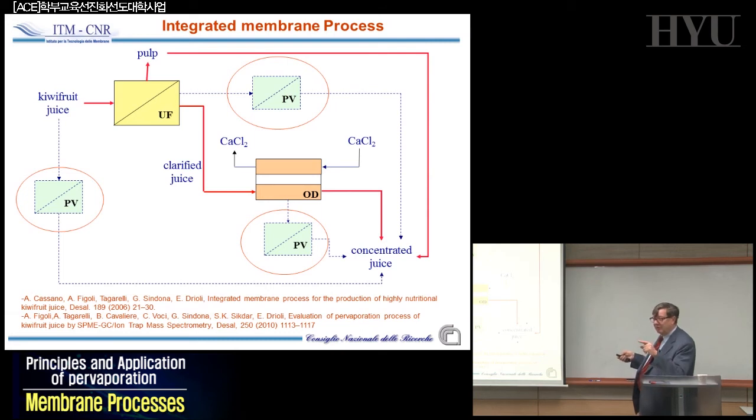But you know that in membrane distillation, part of the volatiles go with the water. So if you have a delicate kind of bouquet, some wine, etc., you don't want to lose this. So what they're doing here is they introduce pervaporation, because pervaporation can selectively remove and concentrate the aroma. And this aroma that you remove here, you will re-add after on the concentrate.